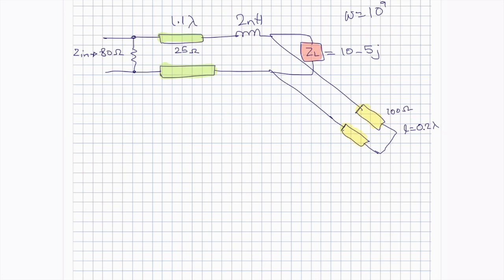So over here we have a bunch of circuit elements such as an inductor, resistor, and Z load. Z load could be anything. It could be the next part of your circuit, or it could be some kind of device that you connect to your existing circuit. And the Z in is the impedance that the new system will see from your current existing system if you connect a different circuit to it.